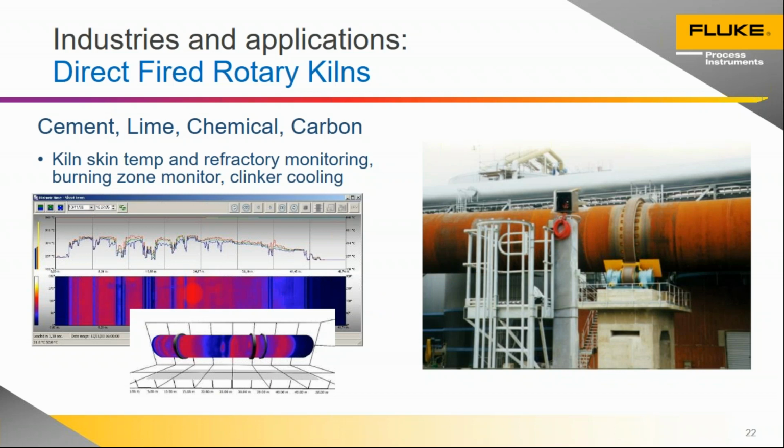We also offer different tools like pyrometers that can look into the end of the kiln and get temperatures of the actual burning zone and flame temperature, wall temperature more directly. But in general, kiln shell temperature is the primary measurement.